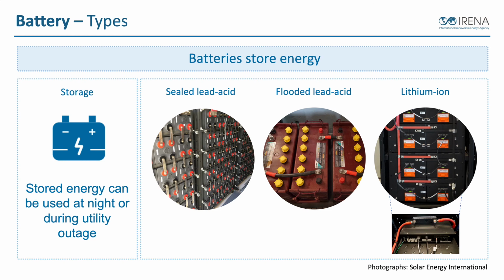One we call a sealed lead acid. It's our basic lead acid technology. It's been around for a long time, but these sealed batteries are designed for very specific deep cycling applications. And so when we look at all of these batteries, these are not a car battery. Even though it's the same technology from a chemistry standpoint, it's not the same type of battery we use to start our car. These batteries are all called deep cycle batteries. They're meant to act different than a car battery. So we want to make sure whenever we're buying batteries for solar applications, we're not buying automotive and car batteries. So these are bigger, more industrial and more purpose-built for cycling like we do in a solar system.